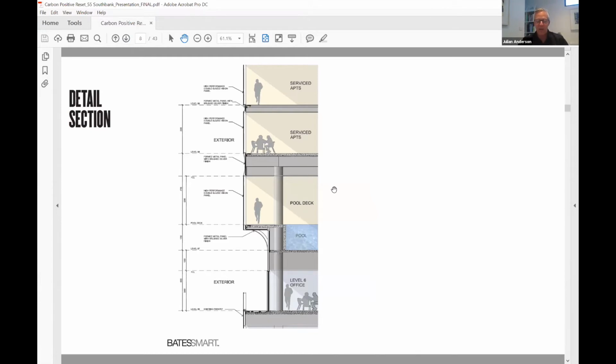The typical floor build-up is 165 millimetres of cross-laminated timber with fire-rated plasterboard to the underside. And importantly, all of the cross-laminated timber used in this building is clad in plasterboard or drywall for fire protection reasons. And the typical floor finish is carpet laid on 19mm lightweight cement composite board.